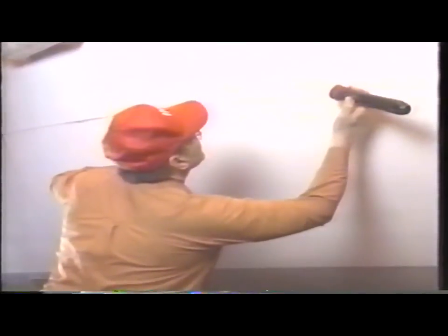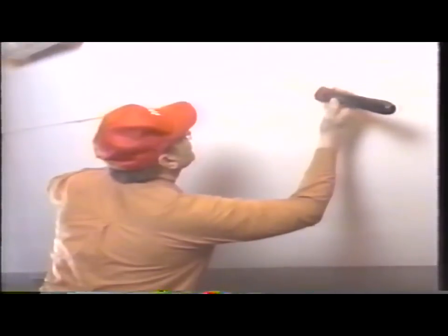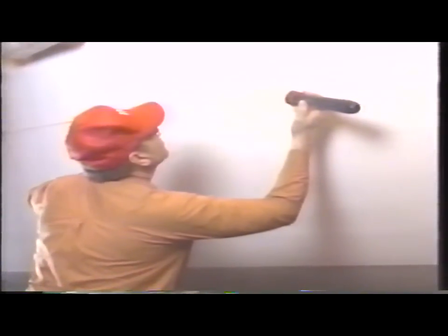Moisture and corrosive agent intrusion also cause corrosion in the seams and joints of fairing surfaces. Any cracking or chipping of the paint coating around seams or crevices must be touched up immediately. Aside from visual inspection, is there any other way to detect corrosion on aircraft skin?